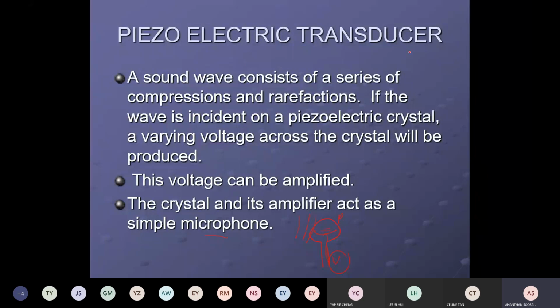But the piezoelectric transducer is not using EM induction, it uses an electric field. The crystal inside will compress and expand to produce a voltage. When the crystal is compressed, the charges will be arranged such that they create a voltage. So the piezoelectric transducer and the microphone are both sensing pressure, but their mechanisms are different. A microphone works by the EM induction method to produce voltage, and the piezoelectric transducer uses the crystal's electric field to create voltage.